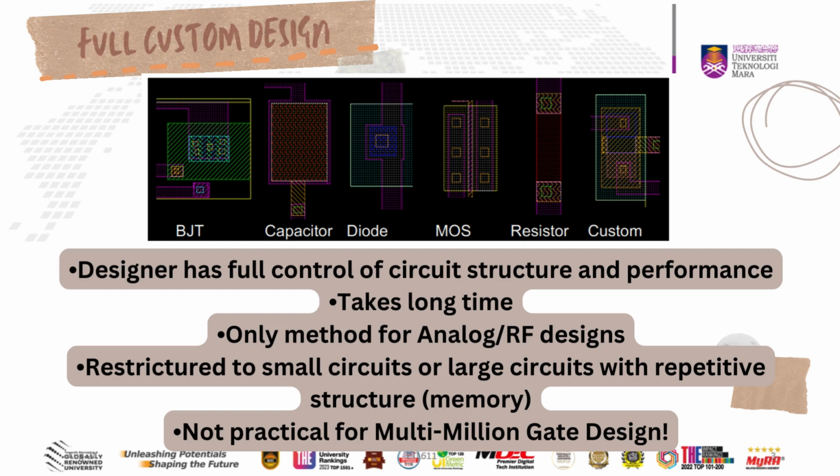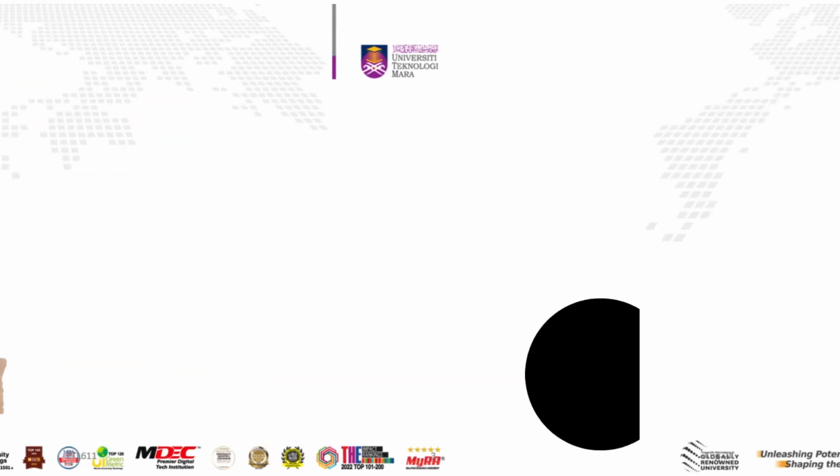In full custom design, the designer has full control of circuit structure and performance. It takes a long time to design, and it is only applied to analog or RF design circuits. It is also restricted to small circuits or large circuits with repetitive structure, for example, memory. It is not practical for multi-million gate design.